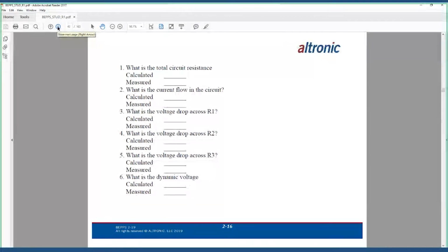In everybody's case, they take a pressure transducer that might be working on a 4 to 20 milliamp current loop, but everybody sooner or later converts it to voltage ultimately, and some of them are not that forthcoming as far as how they do that. We are very open in what we do and the products we do. In fact, whenever we're converting, we use either a 200 or a 250 ohm resistor, and that's it.